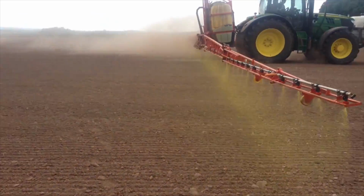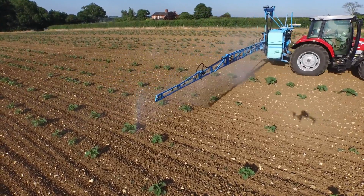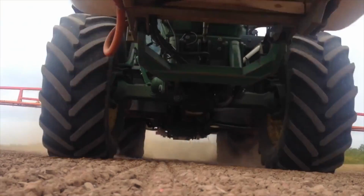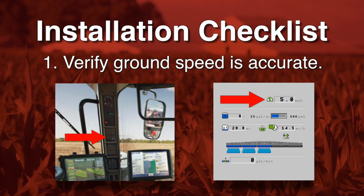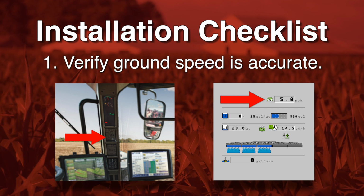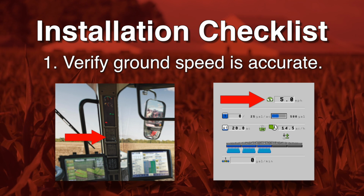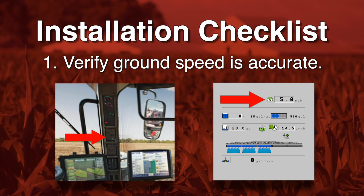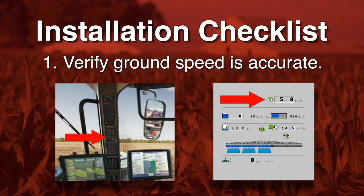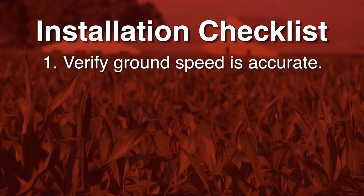The final step of the setup and configuration process is to go through a checklist of 6 steps to confirm and double check that your system is ready for operation. The first step is to test drive the tractor and verify that the ground speed is functioning and accurate. While traveling at a consistent speed, confirm that the tractor display or the tractor A-post speed matches the speed displayed in the universal terminal. There are 2 common sources for speed discrepancy.